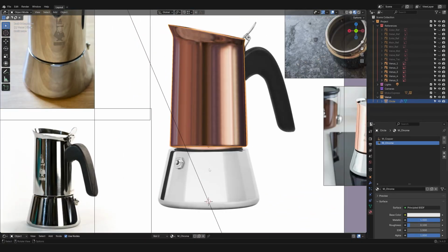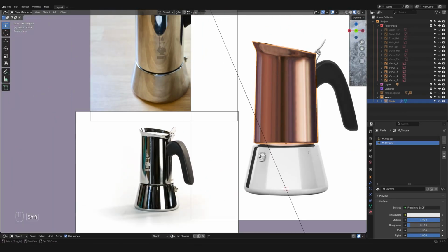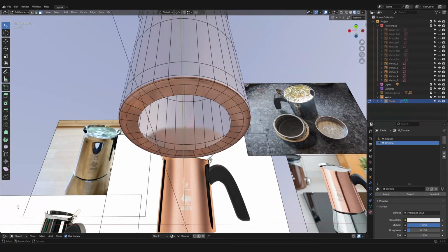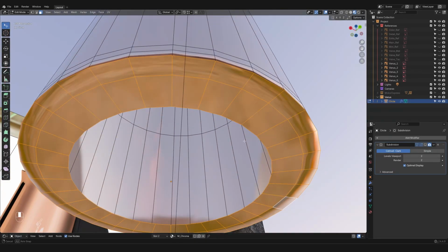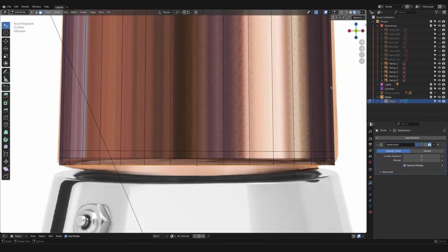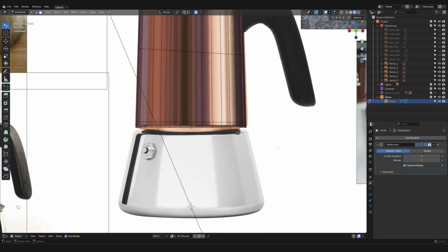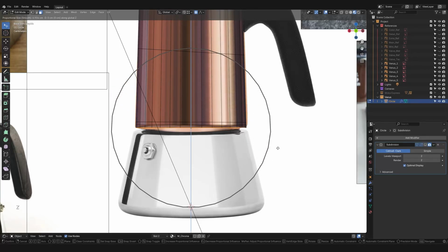So for this part, there is obviously a gap. It's not that big. So maybe we can go in, press 3 to select the faces, Alt and select this one, Shift and select this one. And we might want to check that we have everything that we need. And we do. So from here, I am gonna press O for the proportional editing, G, make it bigger, Z,